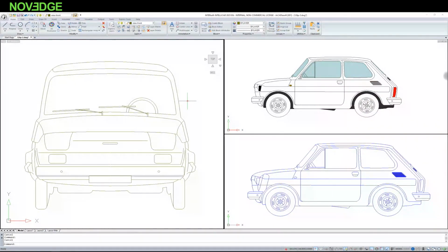You can have, for example, a view or cross-section of a building drawn in one scale and a detail drawn next to it, which will be several times larger. You can define and compose it yourself. The viewports, as you can see here in this example, are different areas of your project that you can show in many ways, helping yourself in the drawing.